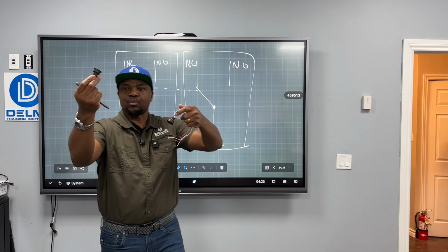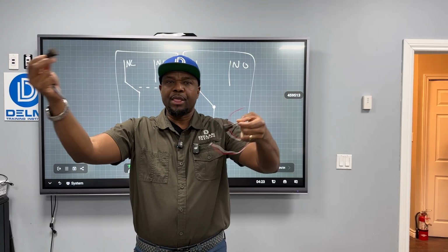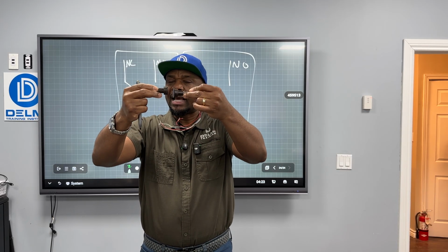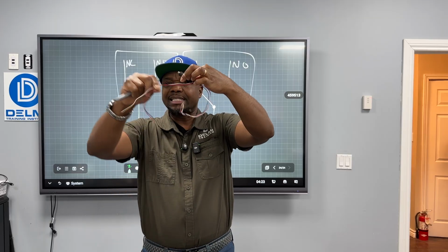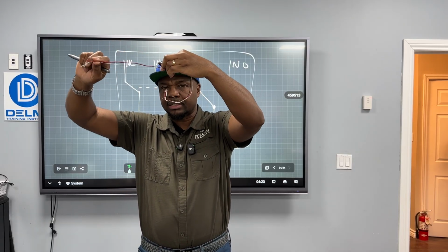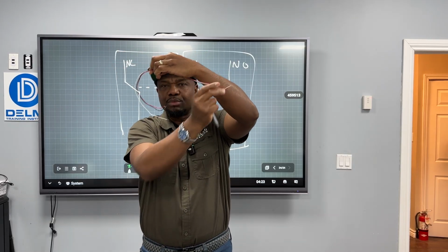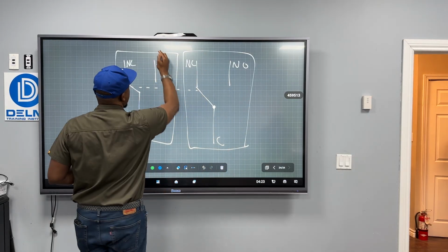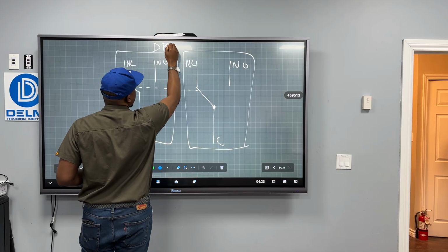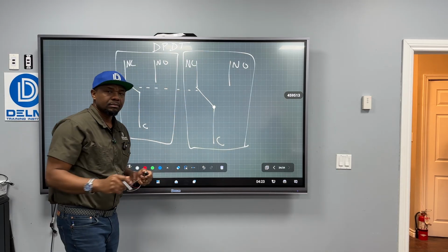So this is what is going to be on the door. When the door closes, it's going to show the system that the door has been closed. And I can send this to my access control system, and I can send that to my burglary system just using one system. And this is a double pole, double throw. Any questions?